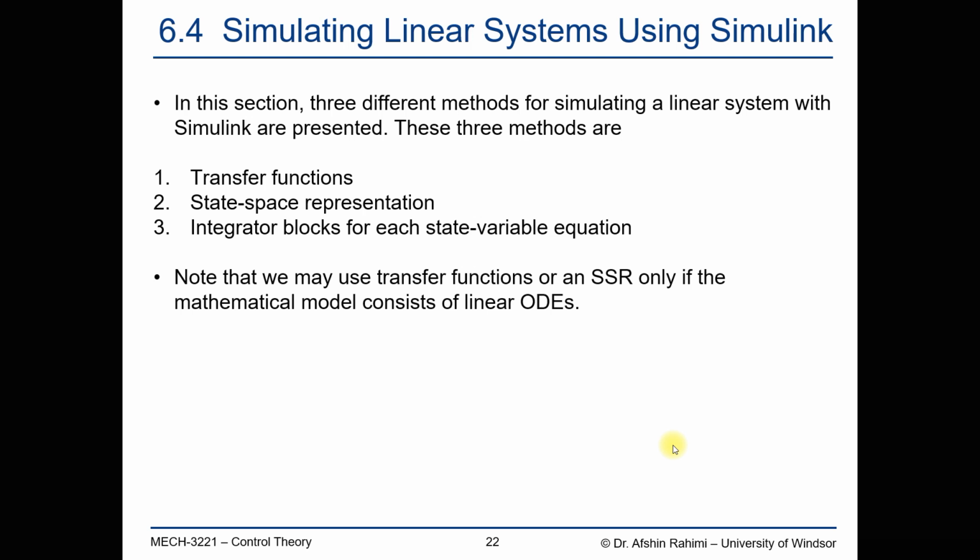These 3 methods are using transfer functions, using a state space representation or SSR, or the integrator blocks for each state variable equation. Note that we may use transfer function or an SSR only if the mathematical model consists of linear ordinary differential equations or ODEs.